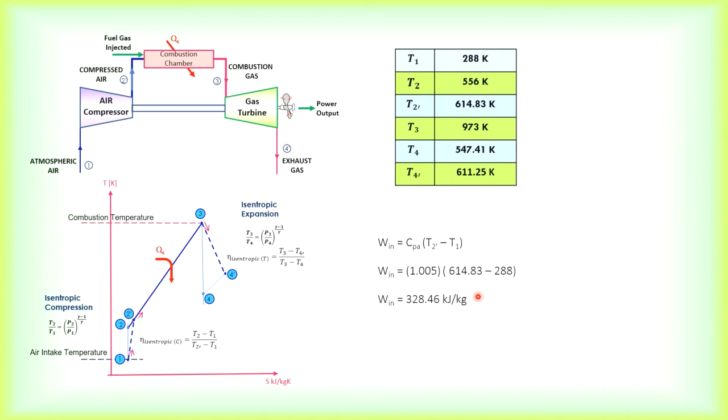Of course, we need work in, work out, and heat supply. So the net work out will be equal to mechanical efficiency times the net work. This term we have not looked into recently. It is usually used when you have any shaft work involved. Usually the gas turbine is used to drive the air compressor and the generator, so there will be power transmission loss due to friction.